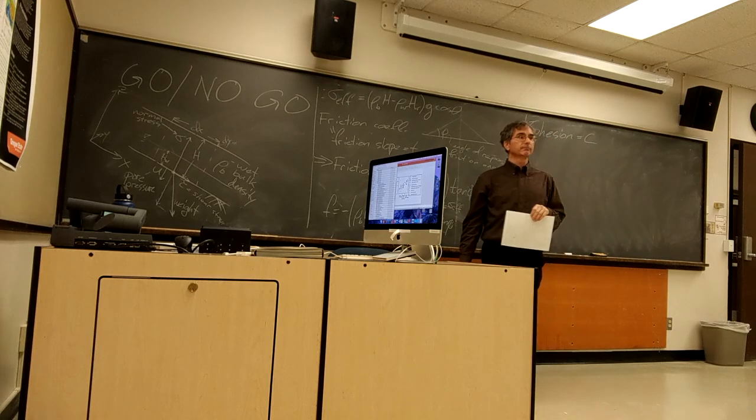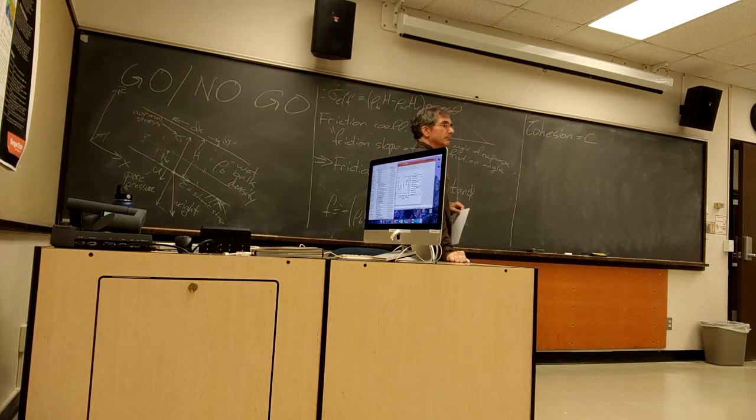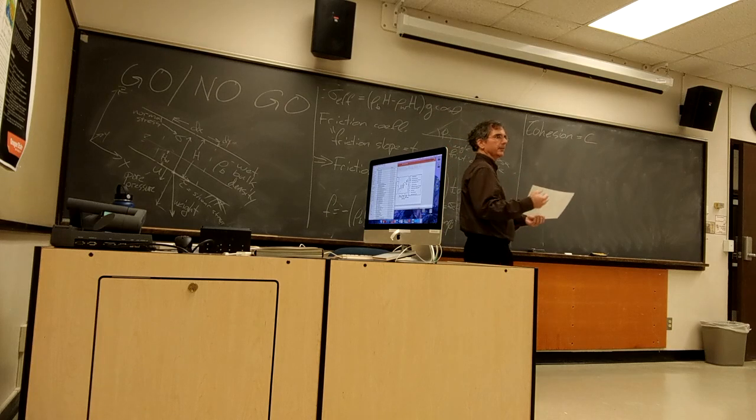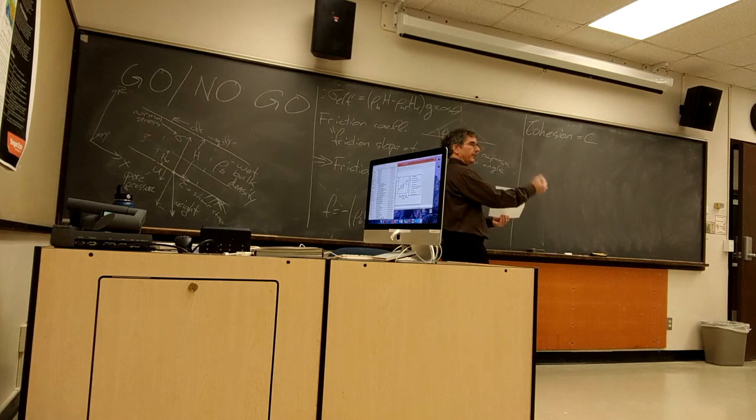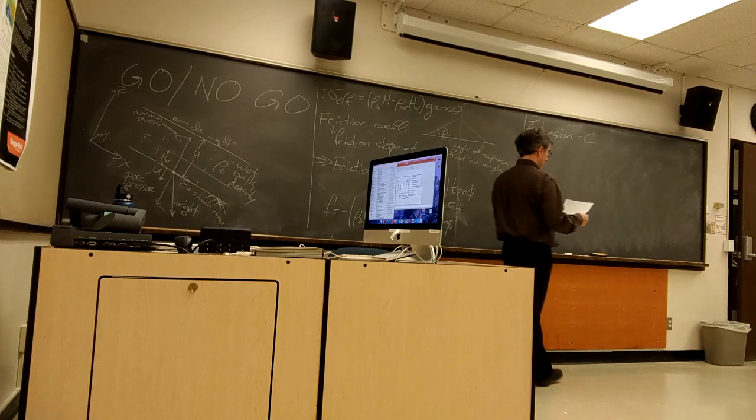Give it a small c. Yep, that's it. It's hard to measure. Sometimes we effectively measure it by what it must have been for something to not happen or something that did happen. If we know everything else, then the cohesion couldn't have been greater than this because it did fail, or cohesion must have been greater than this because it didn't fail.